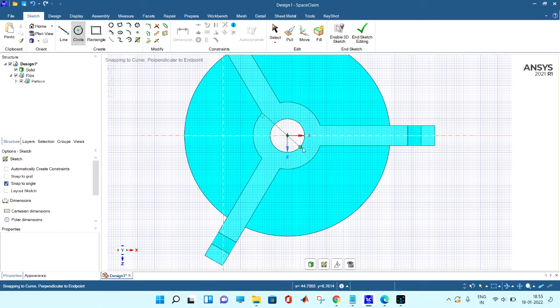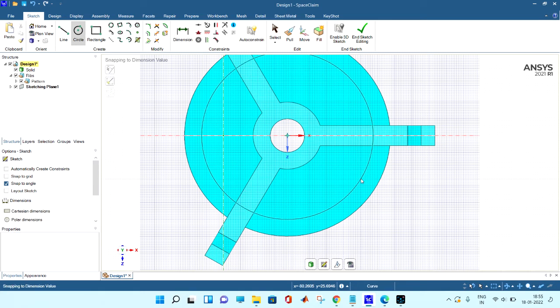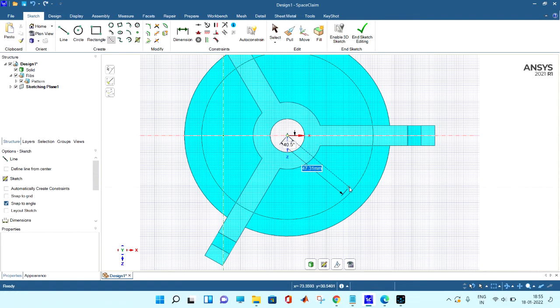For the holes, that has to be at a diameter of 100 mm, and it should be at 30 degrees. It is showing 40 degrees, 20 degrees. No, I want 30 degrees. First of all, tab 30 degrees, tab. I reach this here. I click it here. Then I'm saying okay.